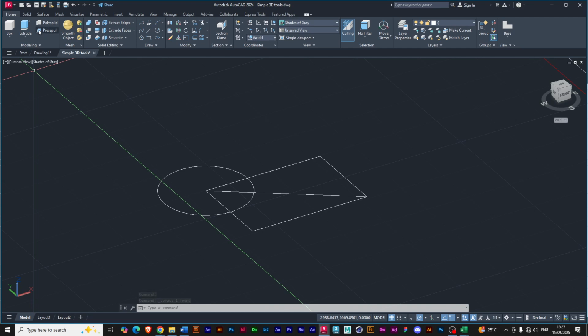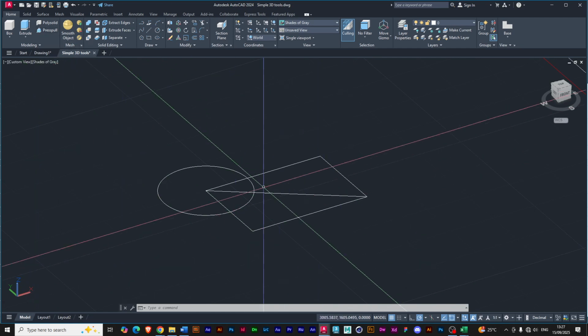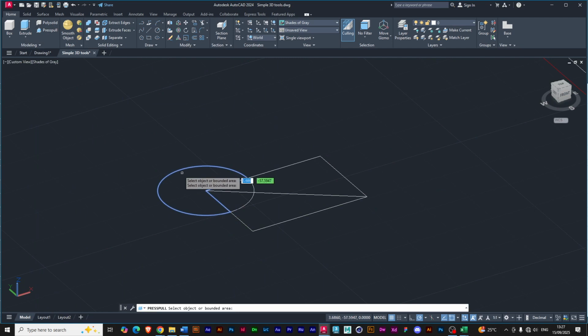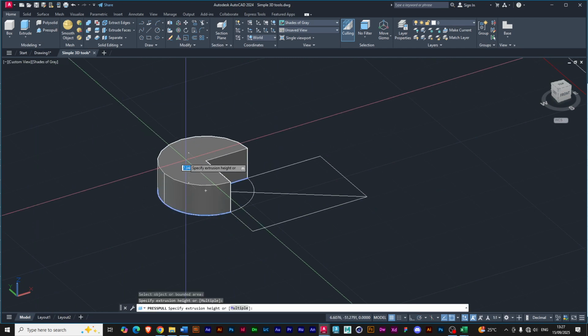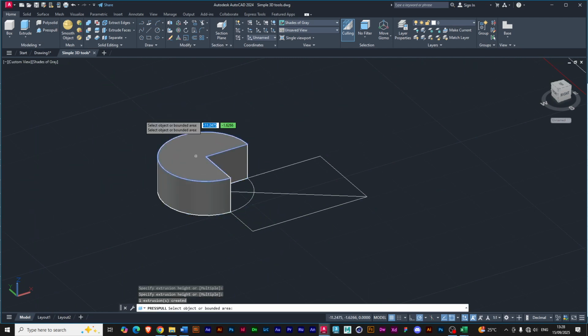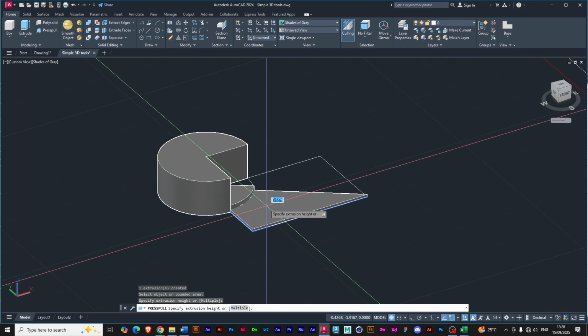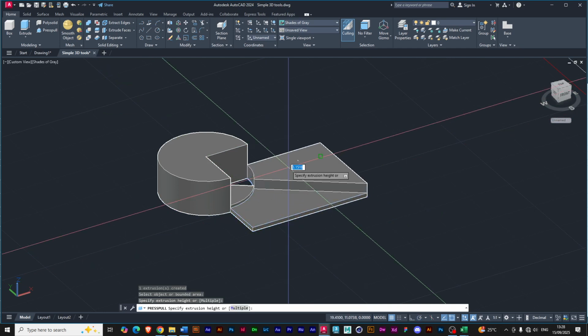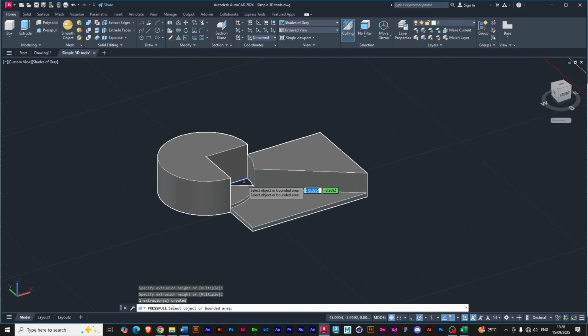So you can keep press pulling and press pulling and press pulling. If I click this press pull, it's still active until I determine that I'm done. So after I'm done, I have to press enter.